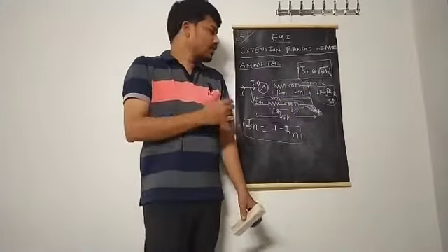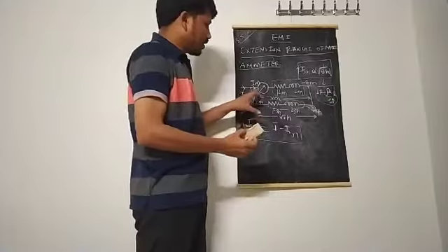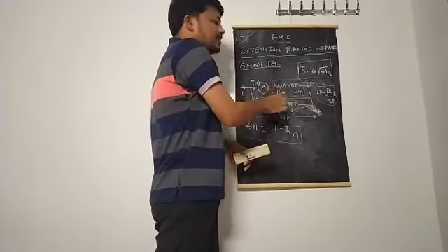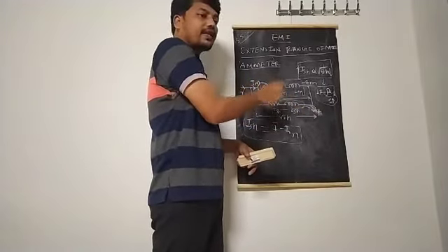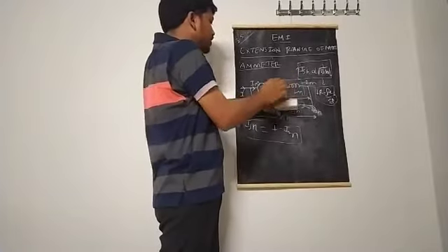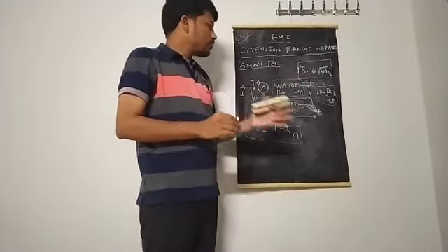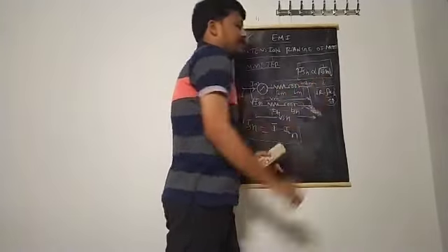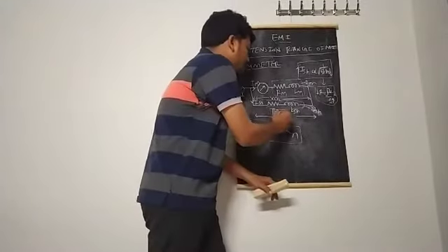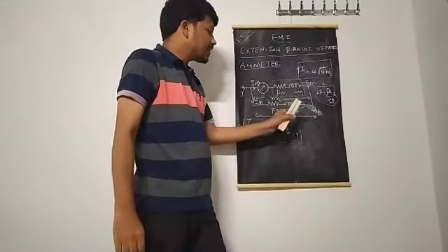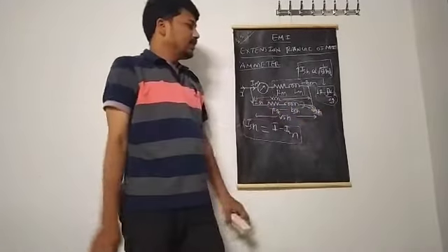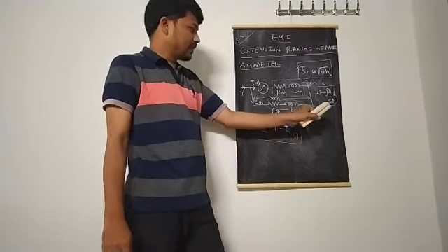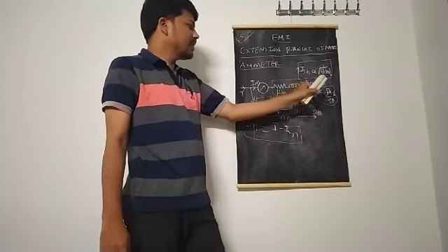So coming to the derivation here, I think all of you are clear on this topic now. This is the complete equivalent circuit of the extension range of moving iron meter used as an ammeter. Without the ammeter, the equivalent circuit of the moving iron meter is only the upper part. To solve this problem, RM and LM is nothing but impedance. Generally I take it as ZM, the impedance of the meter, and RSH and LSH is the shunt impedance, which I represent as ZSH.